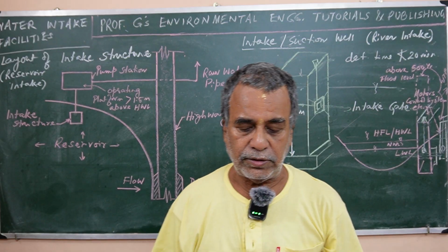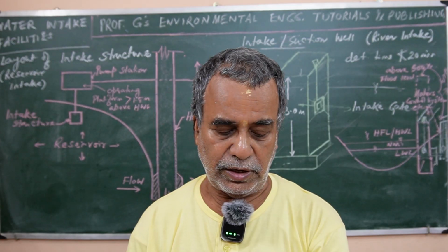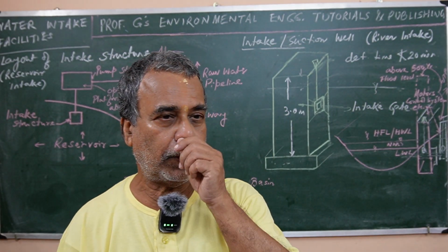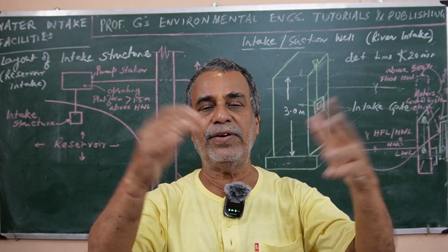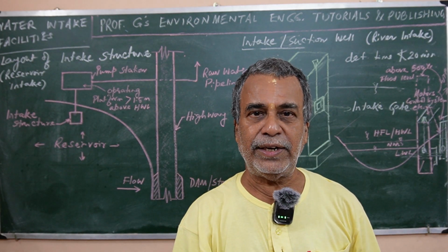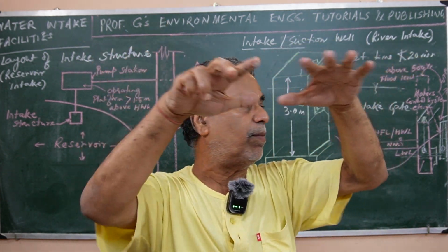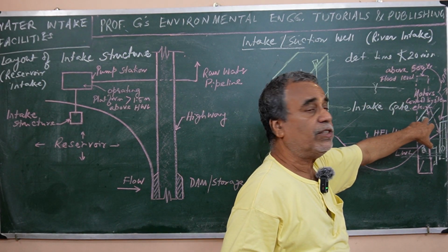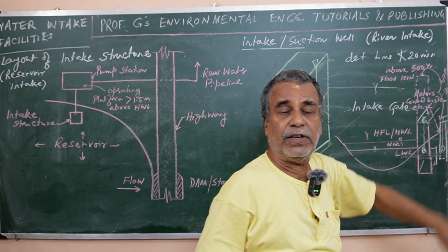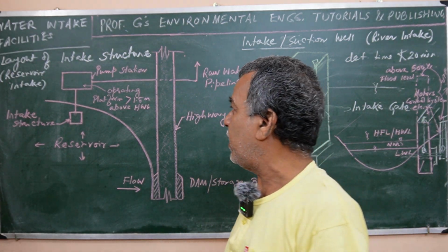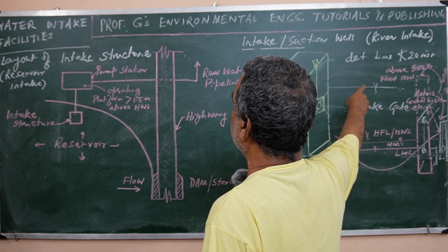Usually, in different countries, different systems are followed. The American system, they consider a 500 year flood, and accordingly they set the elevation of the platform on which the pumps, motors, valves, intake and the pipelines that we have written here are placed. So these are placed here, right?